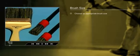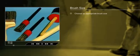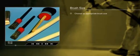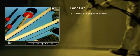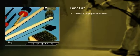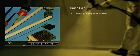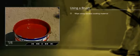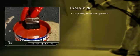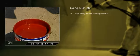A brush of suitable size for the work in hand should always be selected. Using a small brush on a large area makes it difficult to apply an even coating and slows down the rate of working, whilst using a large brush on a narrow area makes accurate working impossible. In practice, the brush is dipped into the coating and the excess material removed by wiping or tapping the brush on the edge of the container as it's withdrawn.